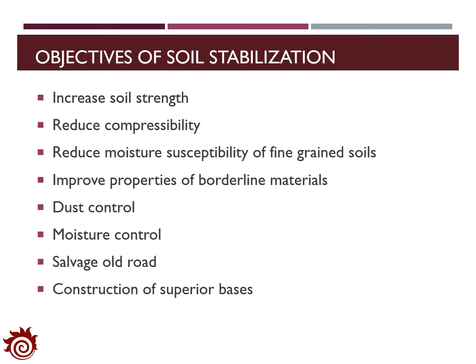In general, soil stabilization is proposed to improve the soil strength and reduce the compressibility. Also, we want to reduce the moisture susceptibility of some fine-grained soils with the stabilization process. We can also improve the properties of the borderline materials so that they can be more stable on the road. Soil stabilization can also be applied for dust control, moisture control, salvage of the road, and construction of superior bases.